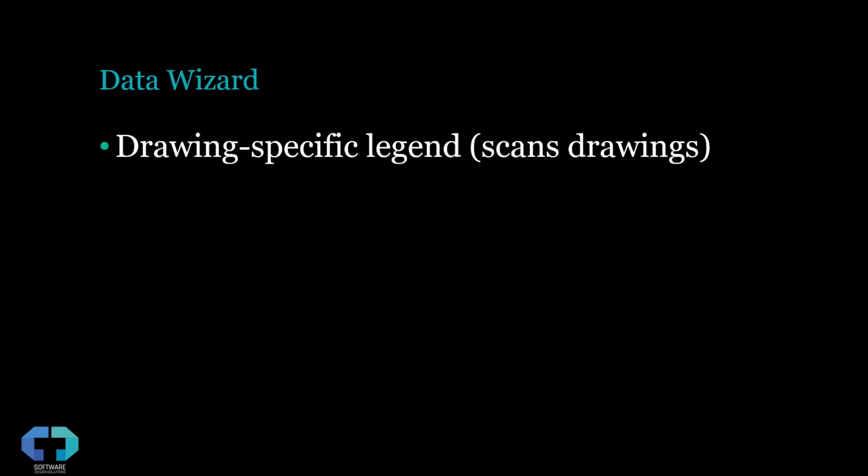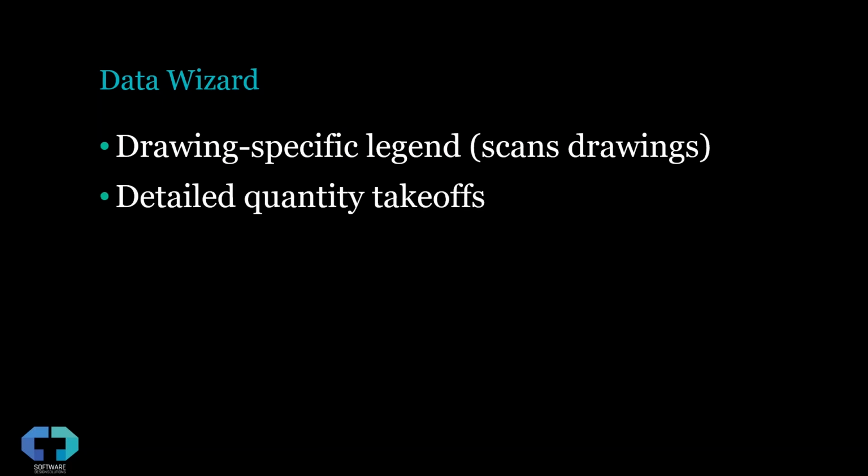So Data Wizard, a number of things. The first idea came from drawing specific legend requirements, right? I want to be able to scan for a sheet or a drawing or multiple drawings and build a new legend. It's one of the most powerful tools in our toolbox. We can do detailed quantity takeoffs. It doesn't have to generate a table in the sheet. I can send it out to Excel. Count up all my curb line, or count up all my seating, whatever it is. We can do that across all kinds of AutoCAD and Civil 3D objects.